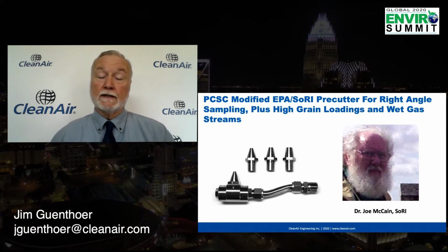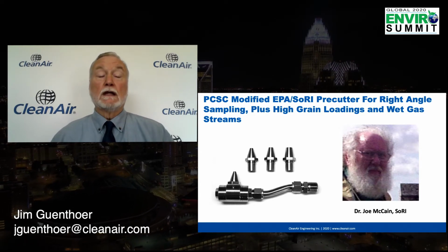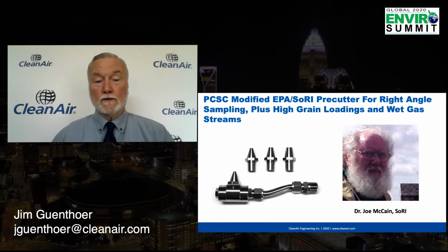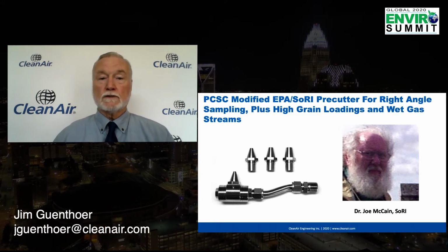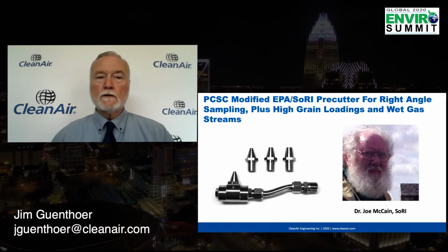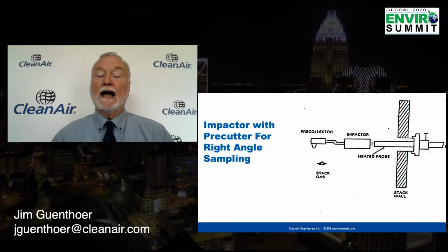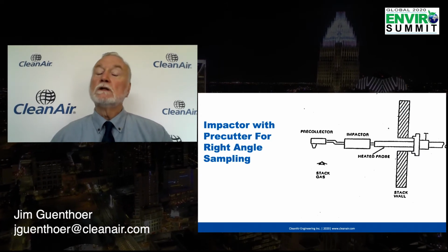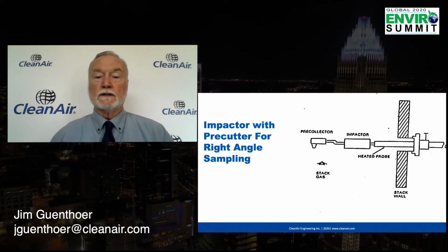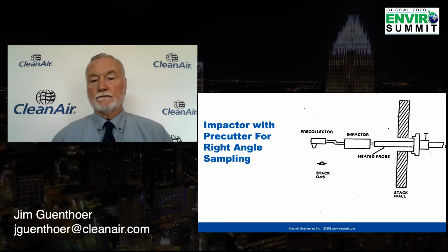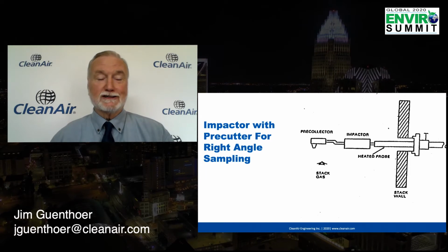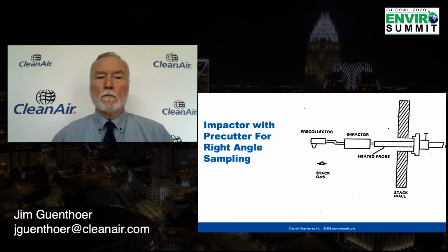This particular head, by the stack conditions, has a specific D50. PCSC is Pollution Control Systems Corporation. That was the corporation developed by Dr. Pilot of the University of Washington to actually sell the University of Washington Cascade Impactors. So as with most very niche industries, everyone knows everyone and everyone's tied together. If we look at the picture now of how the impactor would sample, it is in a more traditional perpendicular orientation. You can stick it in. You don't have to worry if this is narrow here or long here, it's okay. You can still get it in. Again, it fits in a 3-inch ID port. Four is better, but it will fit in a clean 3-inch ID port.